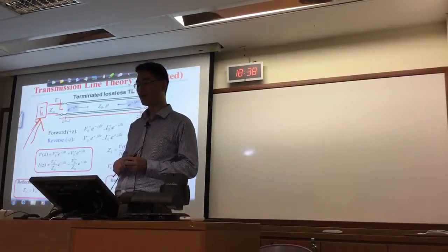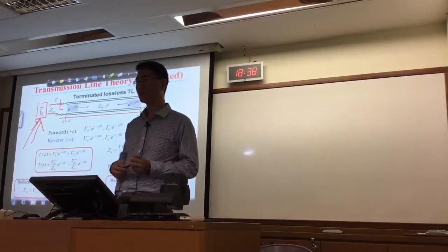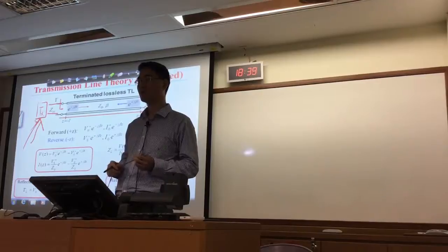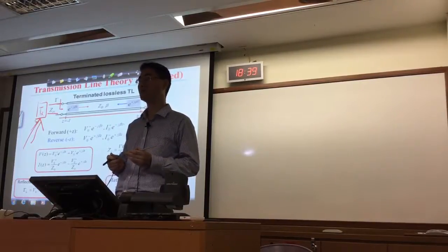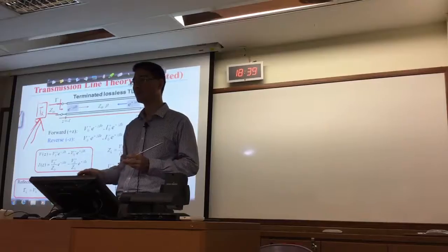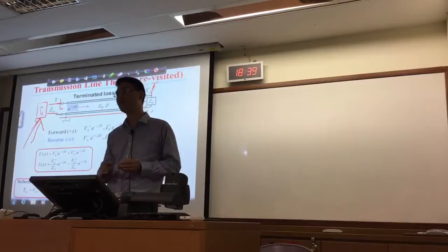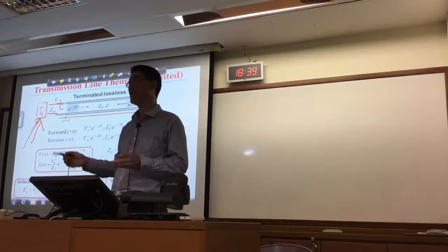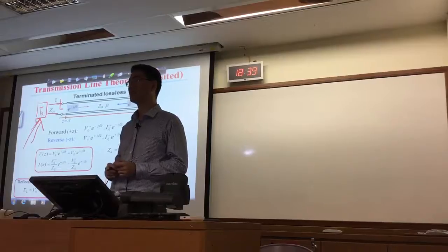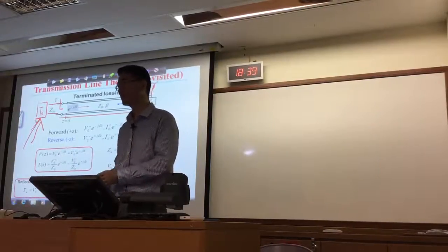So for those, we also need to design the RF system. The idea is to try to minimize the reflection, so the so-called impedance matching is very important. In our following sessions on amplifier design, our task is to design the matching network: the input matching and the output matching, right?